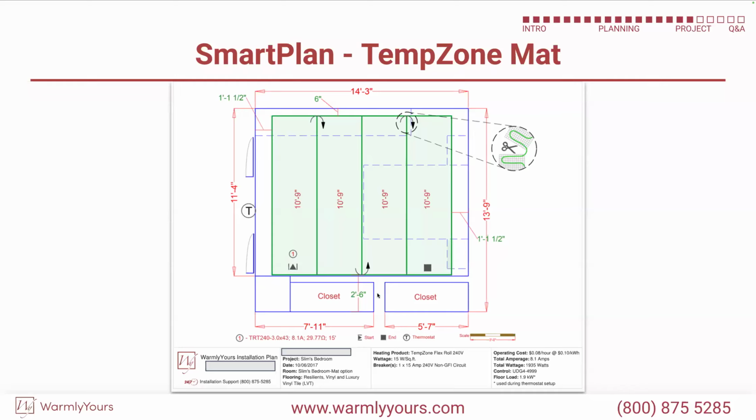Once again, we don't heat closets. The National Electric Code in the United States does not allow the heating of closets, but in Canada they do, as long as you have a control in there to control the temperature. So if this were Canada and we were heating the closet, there'd have to be a thermostat in here. Oh, that's how that works.